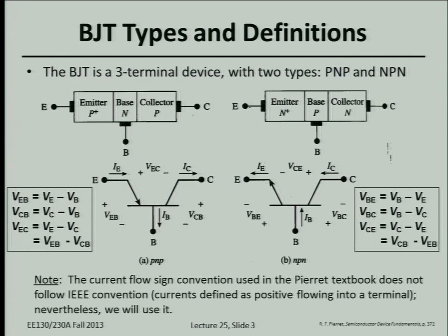So today's lecture will be just short. It'll cover chapter 10 in Pierret, just the fundamentals of a bipolar junction transistor. And for those of you who've taken EE105, I think you covered this type of transistor first. And usually we do cover it immediately after the PN junction because it's natural. We just take 2 PN junctions and make a bipolar junction transistor like this. So a BJT just comprises 2 PN junctions that are back to back. And actually, this is kind of inherent. This PNP structure is inherent in a MOSFET. And that's another reason why in the past we've always covered this device first.